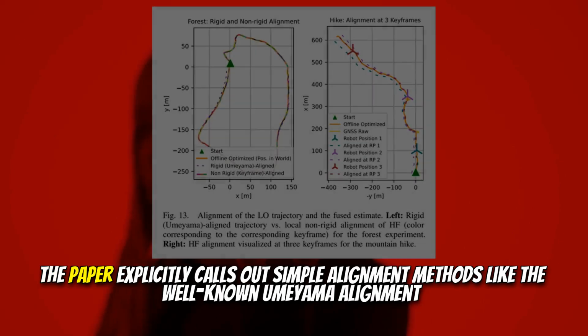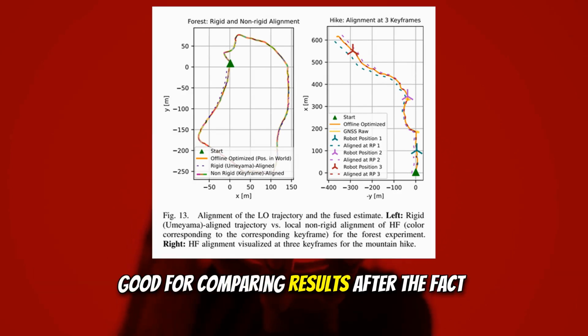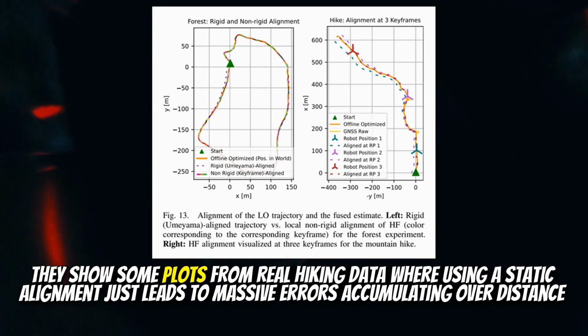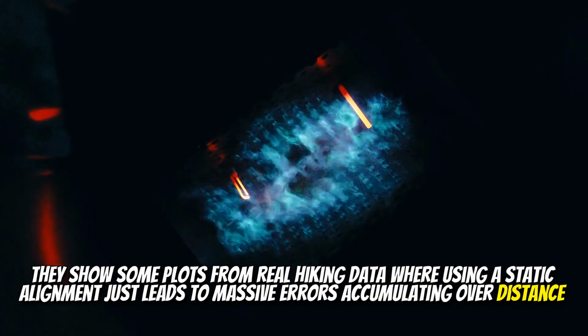Exactly. The paper explicitly calls out simple alignment methods like the well-known Umeyama alignment. Right. That finds the single best rigid transformation between two whole point clouds or trajectories. Good for comparing results after the fact. Good for post-processing, exactly. But totally unsuitable for online estimation where one of the frames is continuously drifting relative to the other. They show some plots from real hiking data where using a static alignment just leads to massive errors accumulating over distance compared to HF.